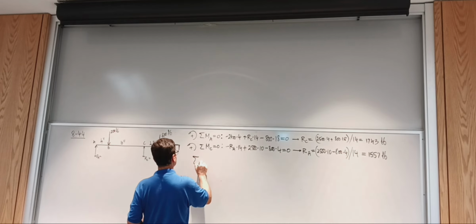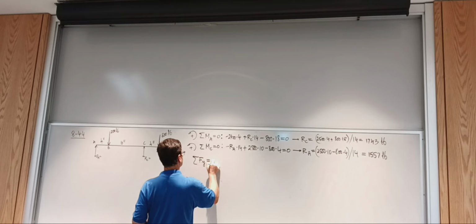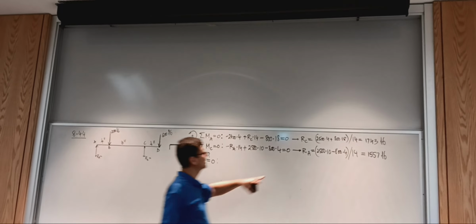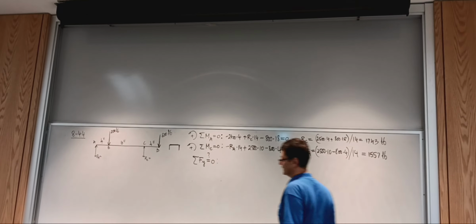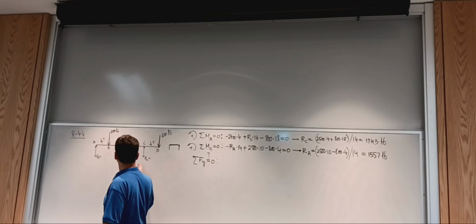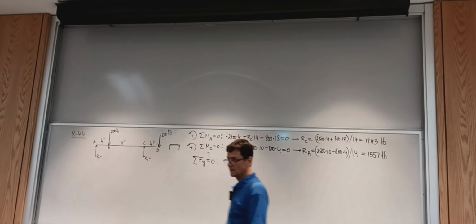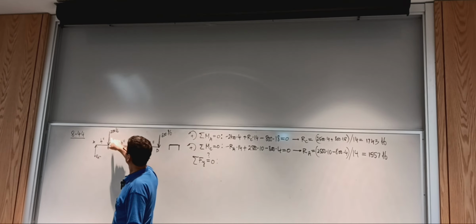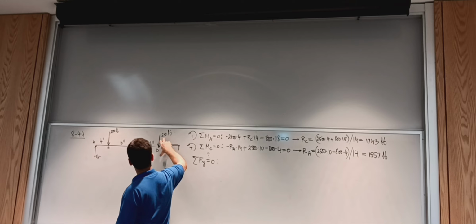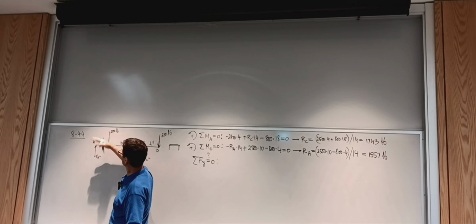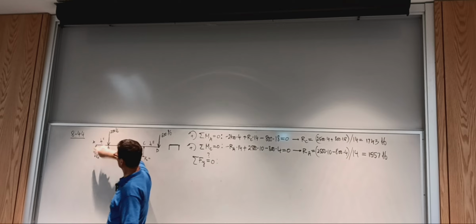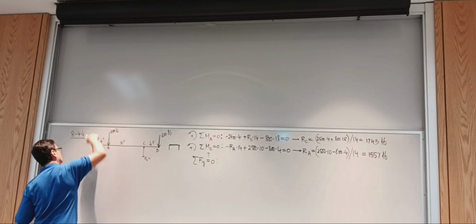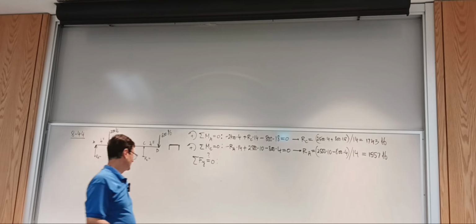We can verify that the forces in the y direction sum to 0. Both RC and RA ended up positive, so the directions we assumed are correct. We don't need to flip any of the reactions. If the overhang load gets larger, you can reach a point where the beam starts lifting off the support, and then RA would end up being a down force.